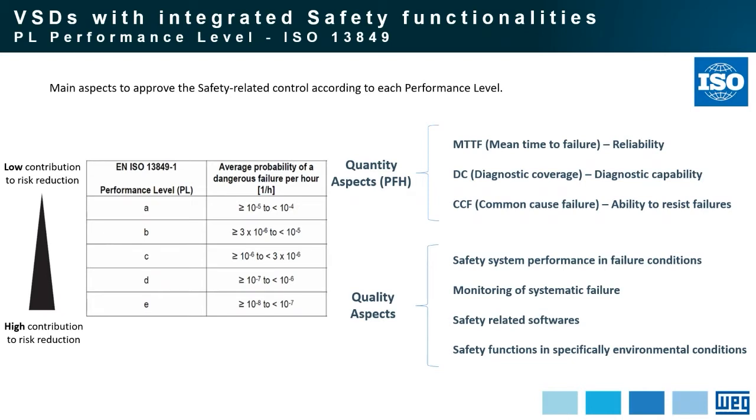And concerning quality aspects, safety functions and especially environmental conditions will also be evaluated here. For example, if specific components will be installed in a high temperature or a very cold temperature, or on the other side, if the component will be installed in a dusty environment, so this component also must be checked and approved to operate in these environmental conditions.